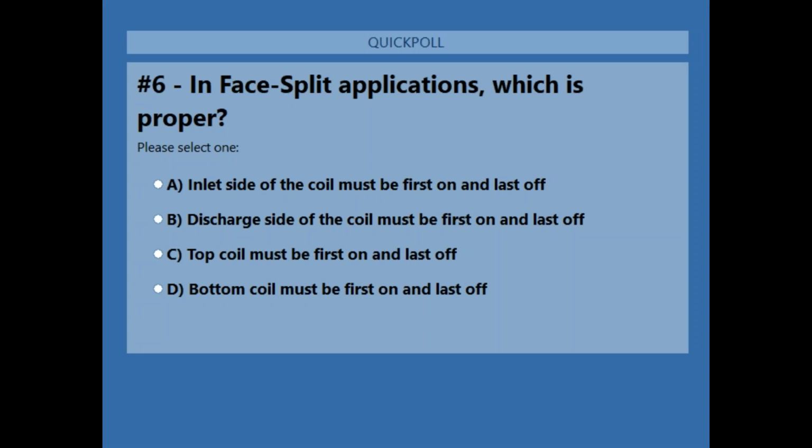Whereas a condenser, non-compressor bearing, is going to have a liquid line connection that you need to connect the liquid line to, and a hot gas line connection. The suction line will all be down at the chiller or whatever you're connecting it to. And really, you have 4 lines between the 4 major components of evaporator, condenser, compressor, and metering device.